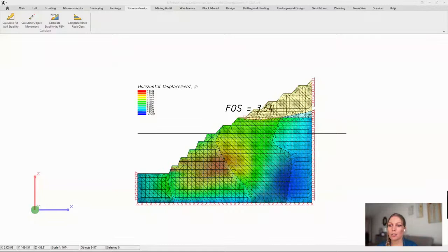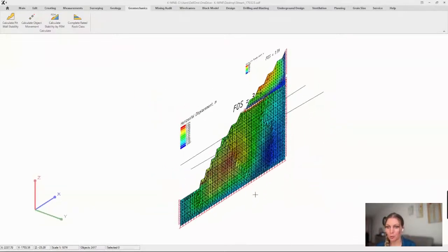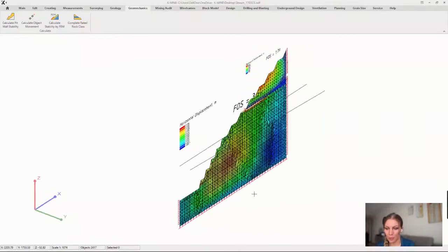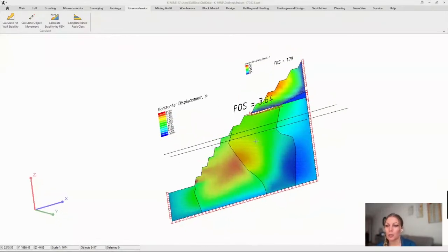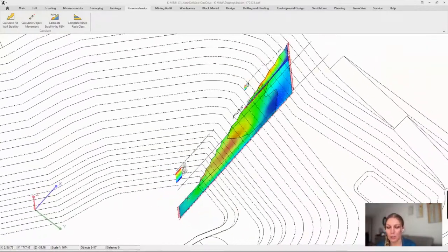The stability factor for the overburden is 1.79, indicating that this section is not extremely stable. While the coefficient is considered normal, there is no need to reduce it at this time. However, we can optimize the factor of 3.64 for the rock formations, which presents an opportunity for improvement. And to achieve this, we can utilize the calculate the slope stability task for our section.